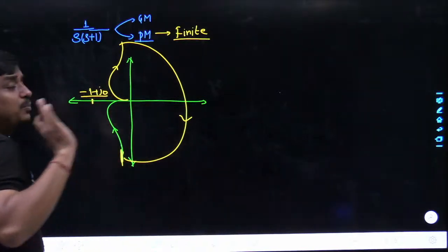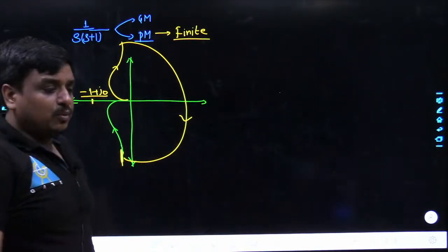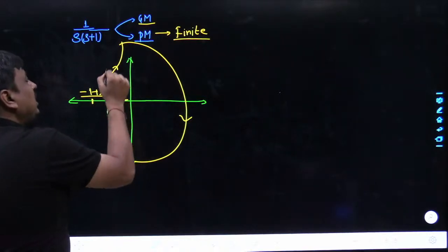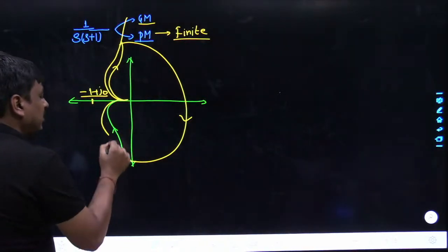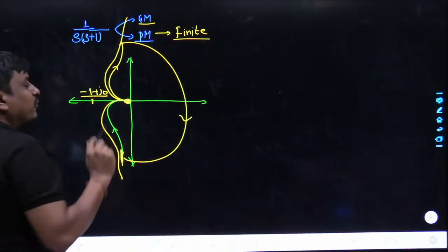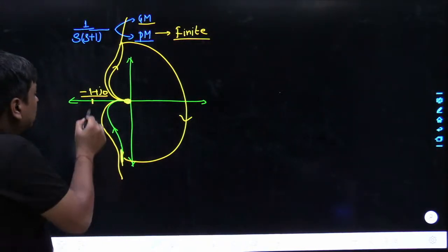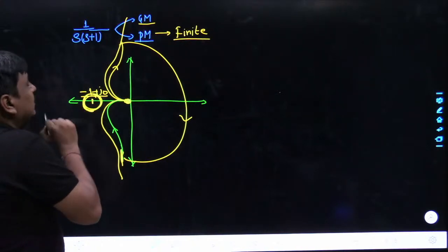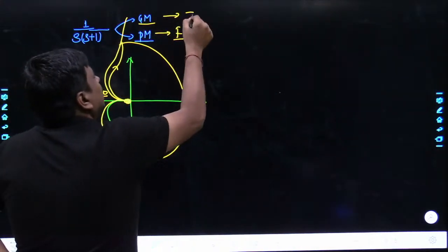That depends on the problem only. But if we talk about the gain margin, if you keep increasing the gain, what is happening is that still at omega equals infinity, the gain offered by the OLTF is infinity. So for no value of omega would it encircle minus 1 plus J0. It would be infinite.